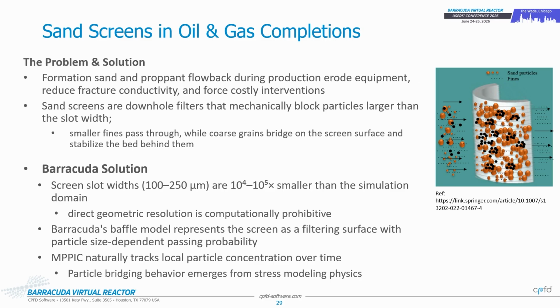All right. Lastly, I've got an interesting topic here. This continues on the line of examples I'm showing with upstream applications. So now this is on the other side, right? Fair enough. I've drilled a well, I pumped in propants, I've settled them down, propped open, I can start producing oil. But you can imagine that as you start producing from one of these wells, some of those propants can start flowing back, and then you also have natural formation sand that's present in the rock that can also start flowing back.